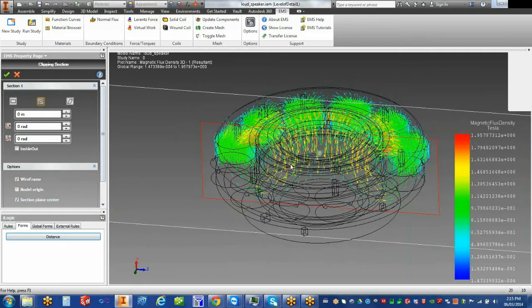When they interact with the voice coil, they're going to create what's called Lorentz force, J cross B. So anytime you put the current inside a magnetic field or magnetic flux density, I use magnetic field and magnetic flux density interchangeably because really they're related by the permeability.